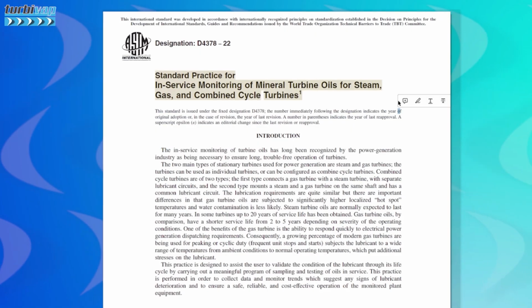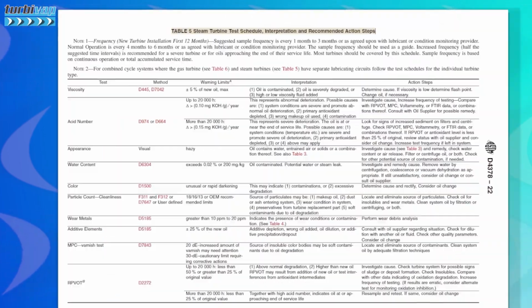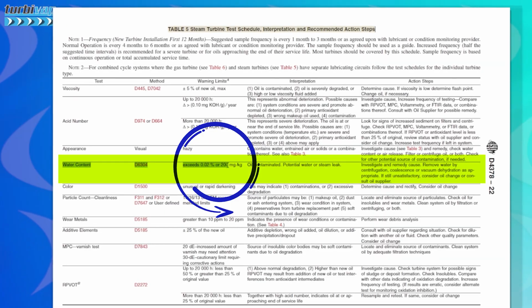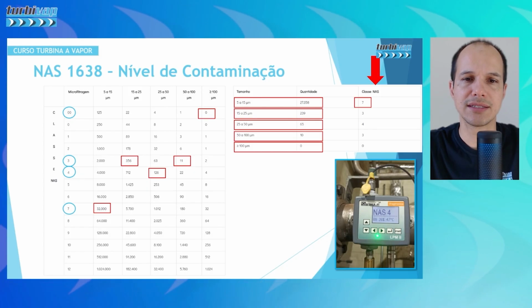Oil analysis as well. Then, collect and send to the laboratory following standards such as ASTM D4378. Contamination analysis standards check for water purity, particulate matter, oil degradation and, crucially, the presence of wear metals. So, finding Babbitt particles, for example, is a clear warning of wear in bearings.